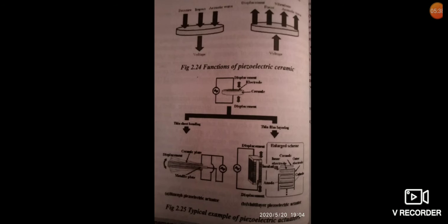For example, when a voltage of about 1000 volts is applied to a piezoelectric ceramic plate with a thickness of 1 mm, a displacement of about 1 micrometer is obtained due to the inverse piezoelectric effect. However, this is insufficient in practice because only a small displacement can be obtained with the high drive voltage. Piezoelectric actuators are structurally processed in order to obtain a large displacement from a lower drive voltage, and the process has thus been put to practical use. So, in order to reduce the voltage of piezoelectric actuators, it is necessary to reduce the thickness of the ceramic plate.